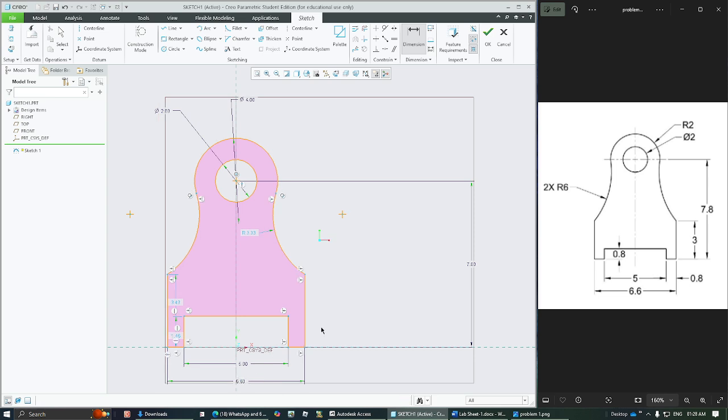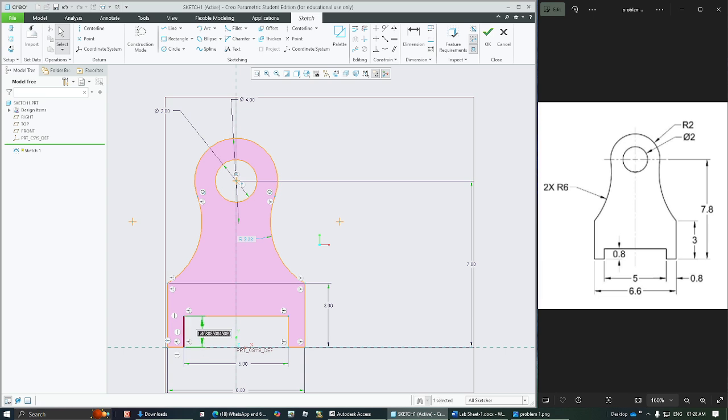Press enter. Now we have this height over here, and we can see that that particular height is already here, right? We just need to change this length to 50. So whatever dimensions you want to use, you can use them as they are. If the dimension doesn't exist, you may have to use the create dimension command. Click on the entities where you want to create the dimensions, and middle mouse click to create those dimensions.